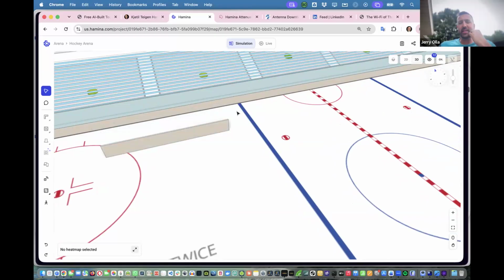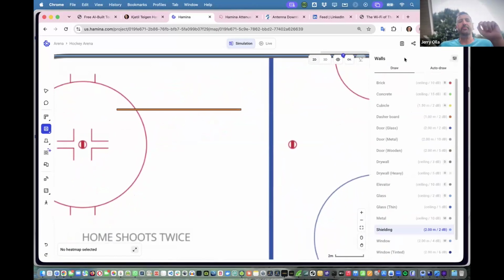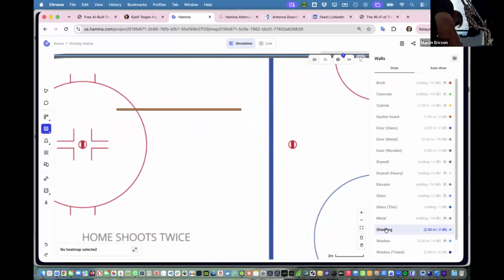So do the exact same thing, except before you put that last left click, when you were drawing the second material, just hold shift while you do it. One, that disables snapping, but two, that disables the swapping of the underlying material.